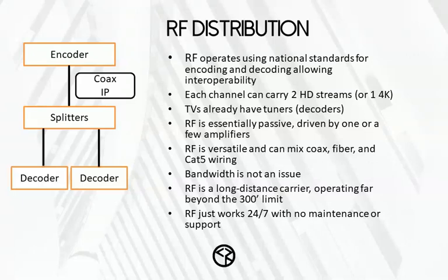And it's 24/7 because there's no real maintenance to do or support. There are no intelligent switchers in between. There are amplifiers that seem to run forever. And so it's a system that's easy to install, easy to maintain. There's just not a lot of technology as far as a single coax going to splitters and taps throughout a system. So it's a very passive distribution system. And that's one of the key things to using RF.